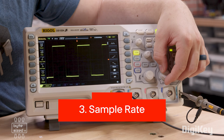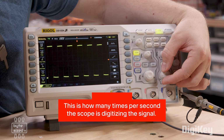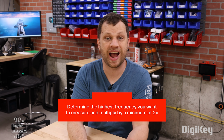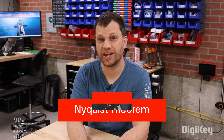And finally, the last feature is the sample rate. The sample rate is simply telling us how many times per second the oscilloscope is measuring the signal and digitizing it. A similar rule of thumb applies for sample rate as well. Your scope will need a minimum of 2 times the sample rate of your highest frequency. But in practice, it's much better to have a sample rate of 5 to 10 times the frequency of your signal. If you want to understand this a little bit better, you can research the Nyquist theorem.